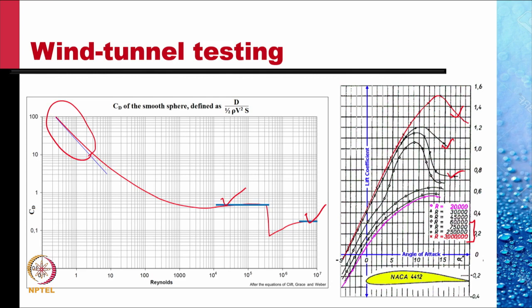A very large range. Most flights are within this range. And over this region of alpha, the three curves are almost coinciding, again confirming the fact that the lift coefficient is quite independent of Reynolds number in this range of Reynolds number.